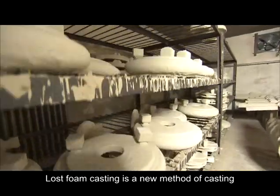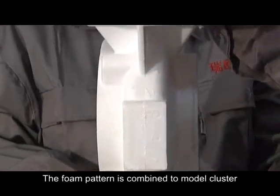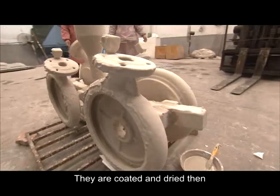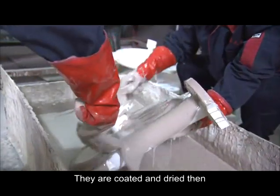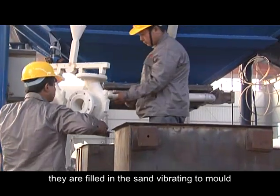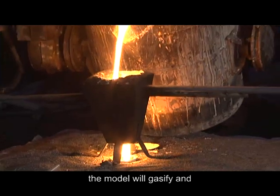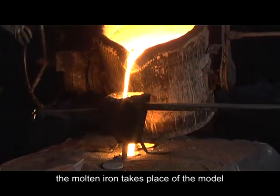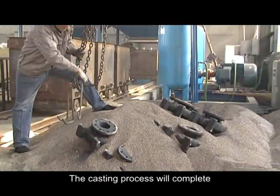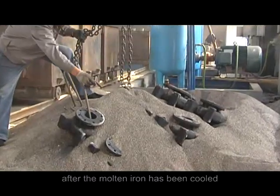Lost foam casting is a new method of casting. In the process of casting, the foam pattern is combined into a model cluster. The model cluster is coated and dried. Then it is filled in the sand and vibrated to mold. The casting undergoes negative pressure. The model will gasify and the molten iron takes the place of the model. The casting process will complete after the molten iron has cooled.